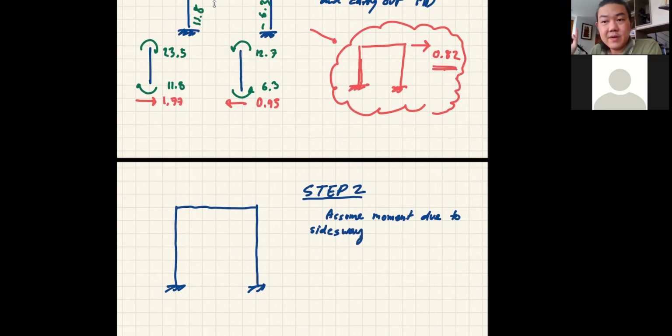Okay. Now we have to make an assumption, but we have to make the correct one. So let's say, because we got a little bit of information from the first step that this frame is perhaps being pushed by this, I'm going to assume that this frame will have displacement to the right equal to delta. Okay, that's what I'm going to assume. Based on this information, now I believe that we all should know that this delta should be equal, correct?